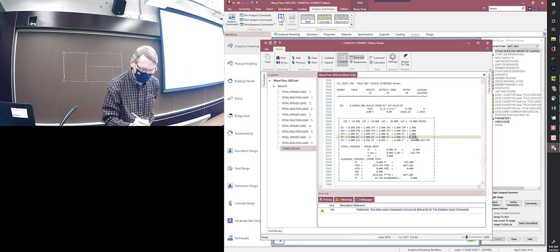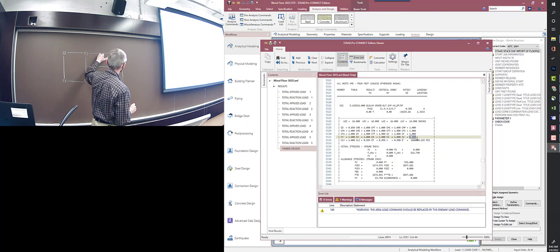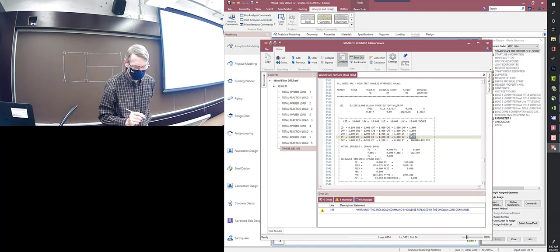It does calculate for our brace, since our bracing is by all the joists, it'll have the correct length for the bracing, so it does calculate at least CL correctly. And then it gives you all these stresses. And it also tells you whether it passes or fails somewhere. Oh, here it is, pass. So it does pass, that's good.